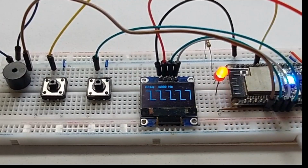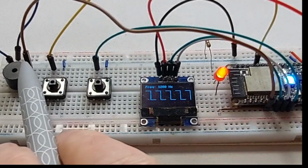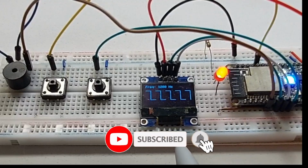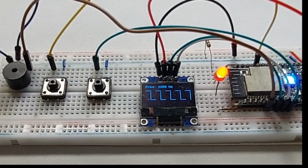Alright, then the output of pin 4, this one here, goes to the buzzer. This is the sound output where the tone function generates the square wave, and you can hear it when you press a button. All this principle works similar to a virtual, well, it is actually a virtual 555 timer. Now I think we will take a look at the code.